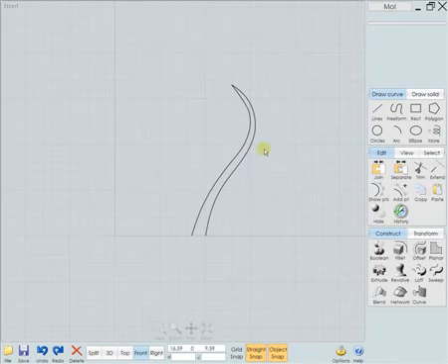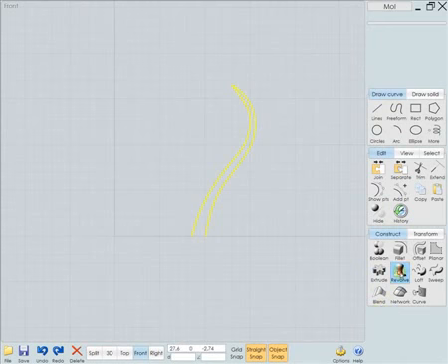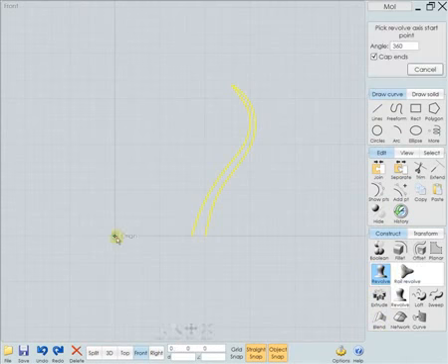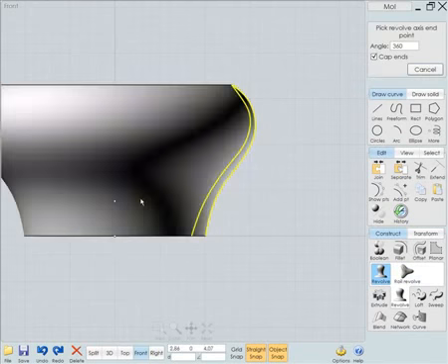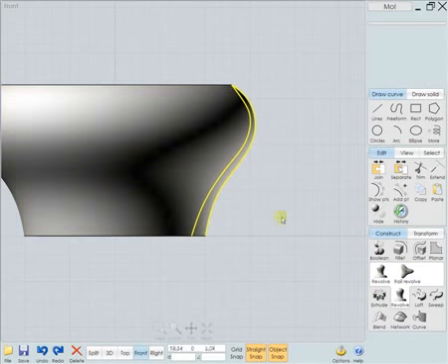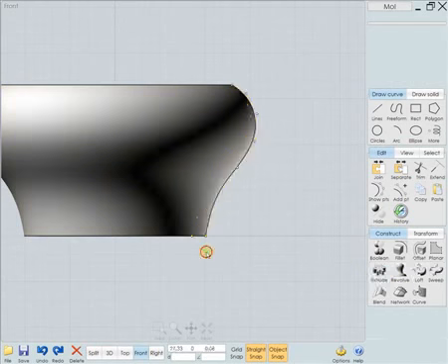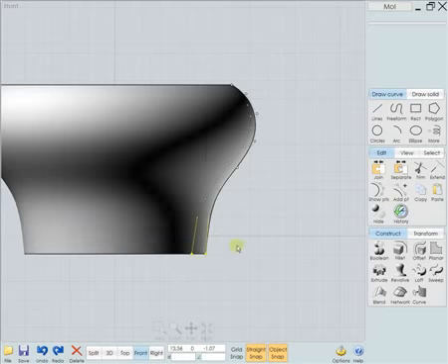So now let's create the base surface for the crown. I'll select these two, come over here to construct revolve, pick the revolve axis over here going upwards, and that will create this surface. I will actually edit these curves again because I want to pull this down a little bit so I'll have this area sticking out the bottom here, and when you edit curves the revolve will update.